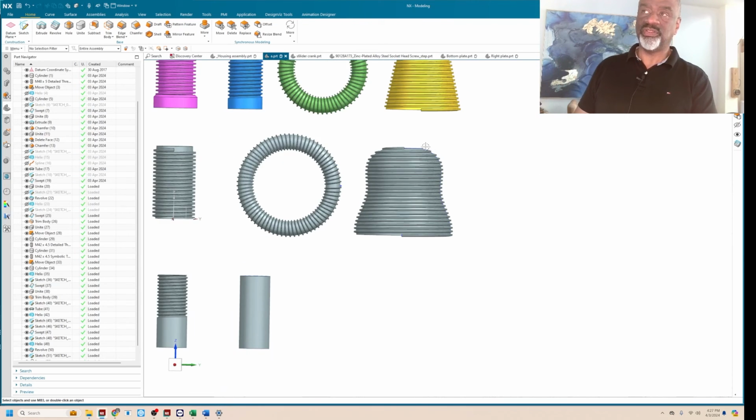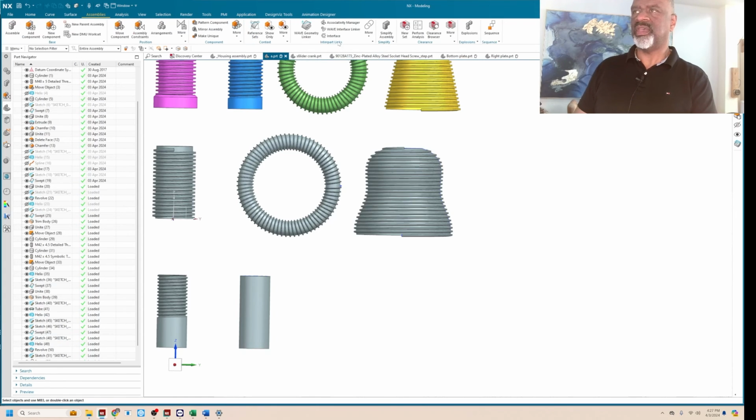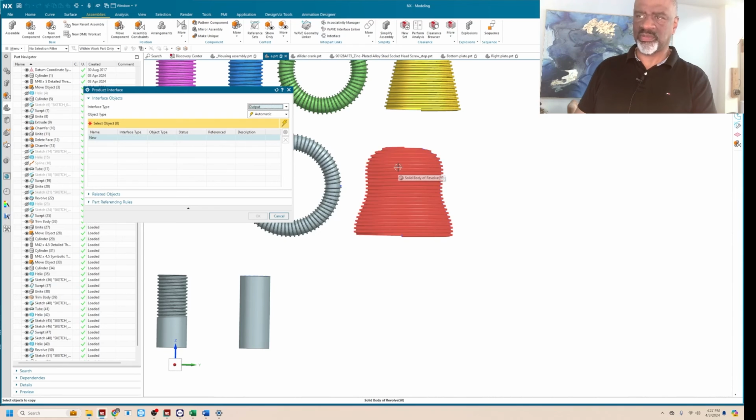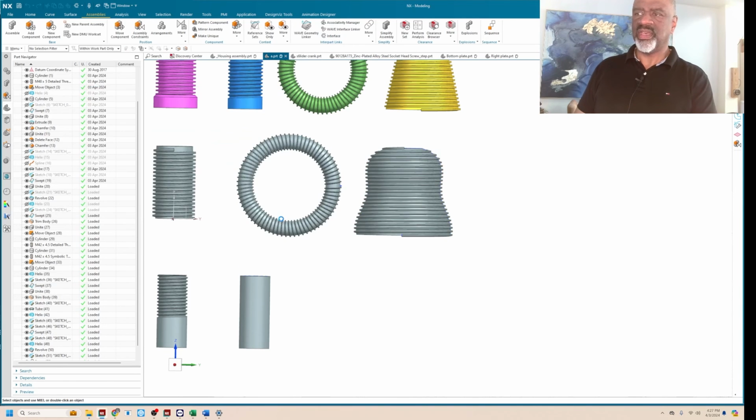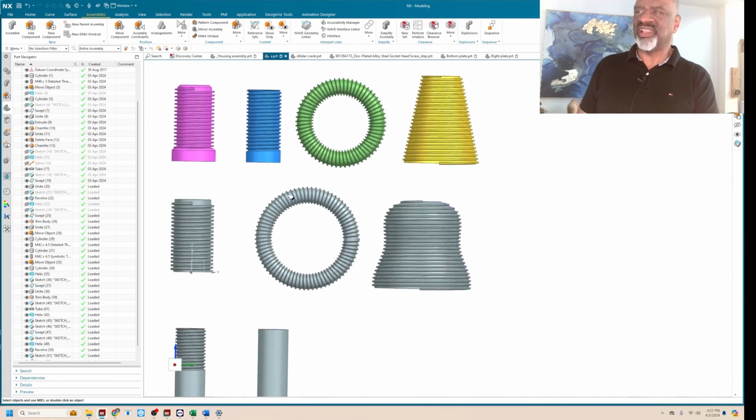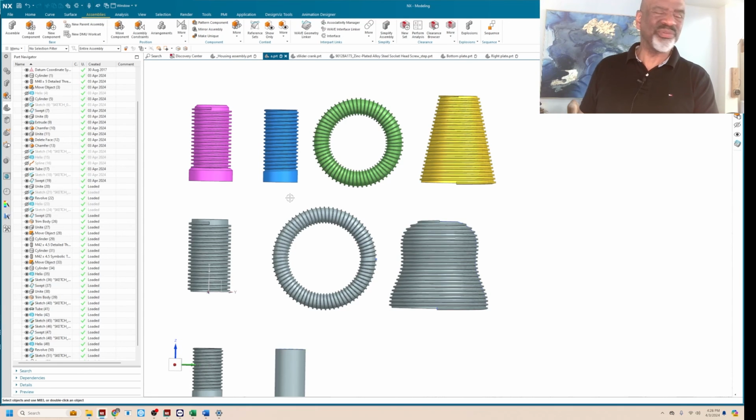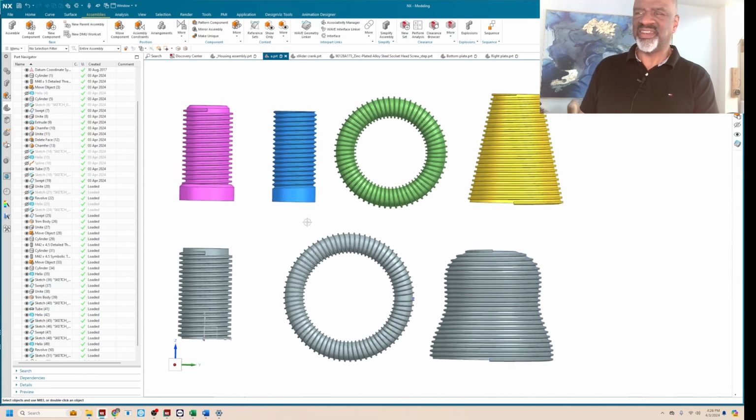So what I might do is go to assemblies, and then interface, and then select one of these as an interface, bring that into the nut profile and do a subtract, and then I have an exact subtract, and then I'd probably offset it a little bit to make a little bit of clearance. Anyway, that is a lot about helical forms and screws and this kind of thing.